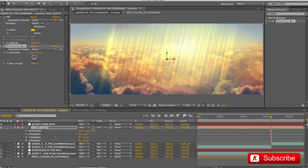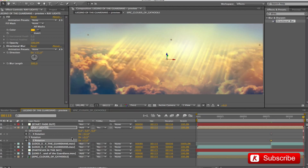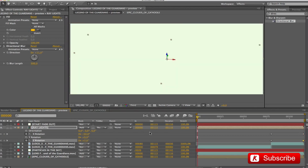Insert a keyframe on the X rotation with the value minus 52 and Z rotation to 7. In 115 frames, insert the following values: minus 59, 11. In frame 0, minus 68, 0. OK, visualize the result.